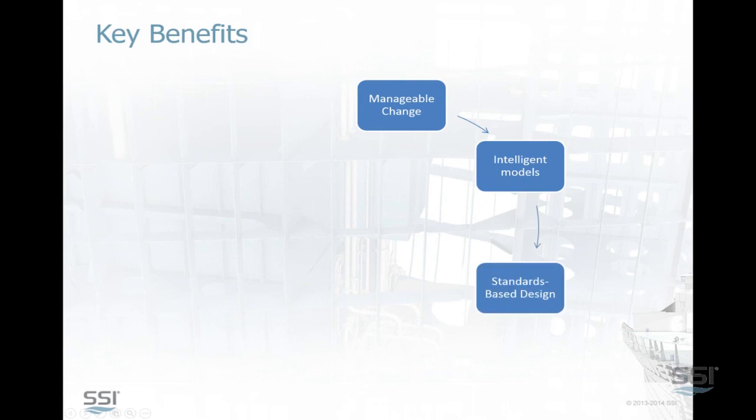Standards-based design. The 3D project model is built using a range of configurable shipbuilding standards, including flanges, profile cutouts, standard brackets, stiffeners, etc. The required standards are either selected manually by the user or automatically selected according to predefined associative rules for each project. As these standards are changed in the library over time, the project model automatically reflects their current state, which is pretty handy.